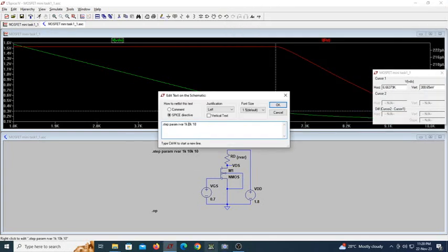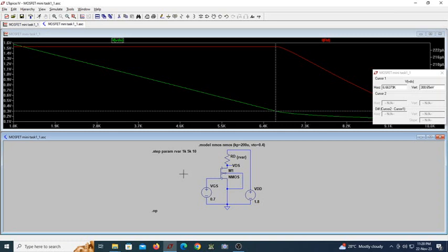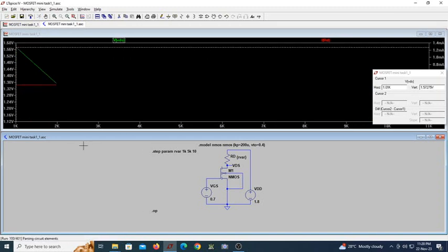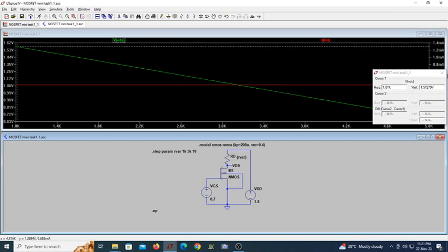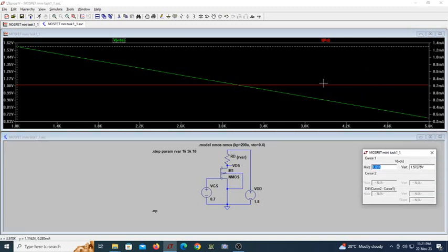If you just run it only up to 5k, since our calculation said that you have to go up to 6.6k, that is the maximum value that you should change. If I run it now, see now, this is hardly 1k to 5k. One thing to observe here is the current has not at all reduced.